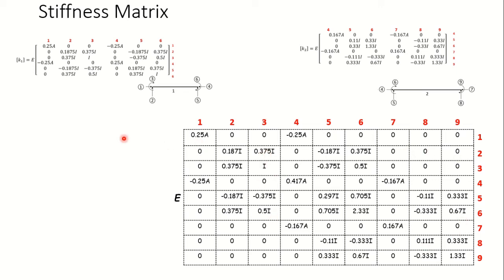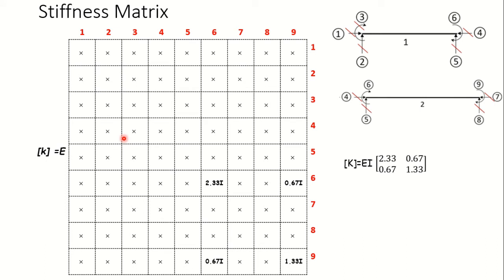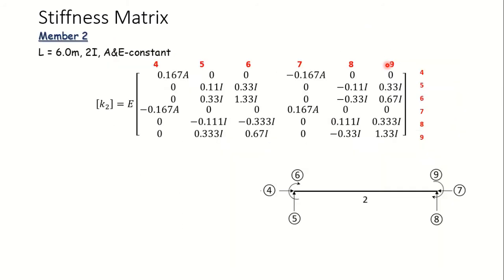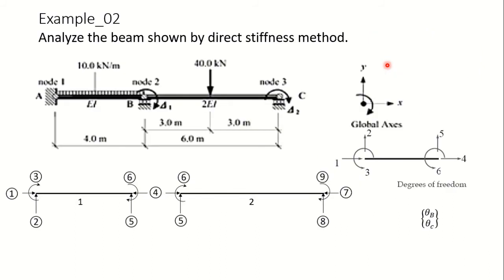Okay, now coming to our beam. Look at the support conditions in our beam. At the first joint, it was a fixed support. So if you look at this beam again, fixed support is provided at A at joint 1. There is a hinge support at B and hinge support at C. So here no displacements are allowed at joint A. At B only rotation is allowed and at C only rotation is allowed. Other than these there is no displacement which has been allowed.